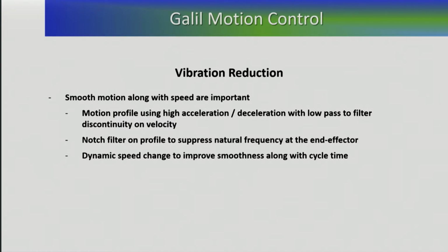In some instances, the encoders do not show any type of vibration, but you still have that vibration, and that happens to be at a very low frequency. Well, how do you address that when you have no feedback showing the oscillations? And that becomes very critical. So you have to take that frequency that is well below your system bandwidth.